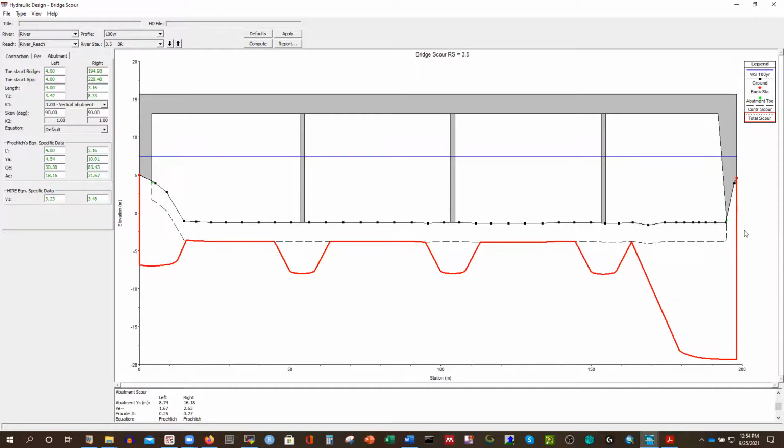If you didn't know this information, then what would happen? This amount of soil will be washed out if you construct this bridge. And if you have a 100-year flood with a flow rate of 6300 cms, and you didn't expect that and didn't construct the bridge after considering all these values, then definitely the bridge will be washed out. So we have to consider that.